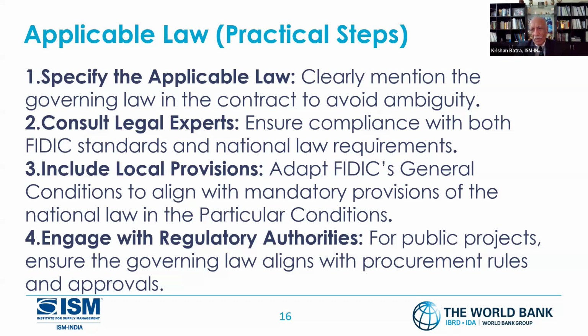Consult a legal expert. Ensure compliance with both FIDIC standards and the national law requirements. The FIDIC standard is there, but we also have to see whether the national law allows all those choices or not. Accordingly, you may have to make some provision changes and include local provisions, so that the FIDIC general conditions align with the mandatory provisions of the national law. In 99% of cases the problem may not be there, but in some countries there may be restrictions, so you may have to modify the FIDIC standard accordingly.